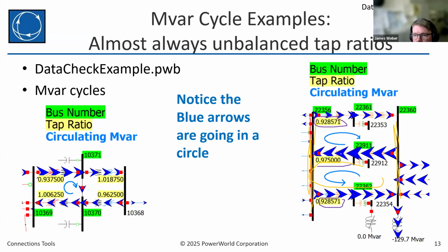And then a third transformer got added. I suspect what happens over time is a case has, in this example, 2 parallel transformers that they set up very carefully to coordinate with each other. And then a decade later, another young engineer is handed, hey, we added a third transformer, put this in the model. They put it in the model. They get all the tap settings and everything correct, which isn't simple to do at the beginning, but they don't make the 2 tap and the 3 tap ratios consistent with each other, which results in the circulating vars.